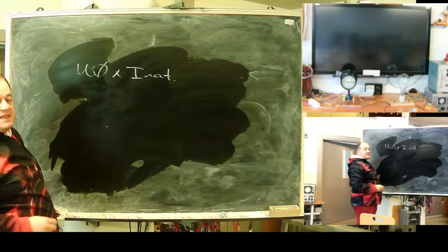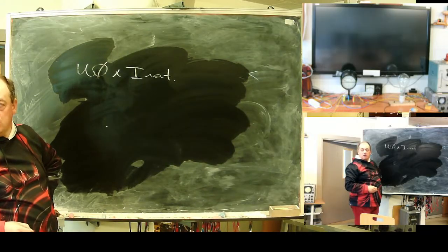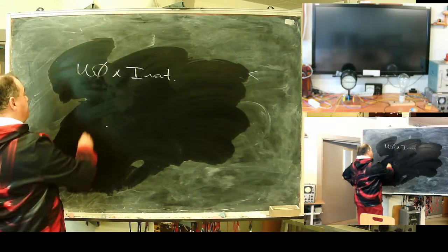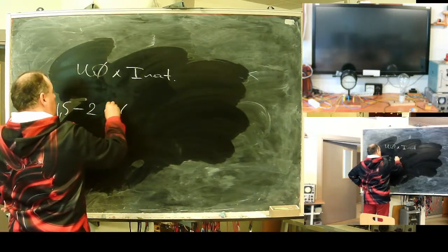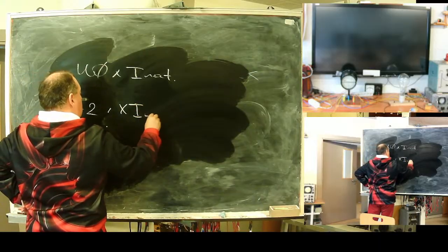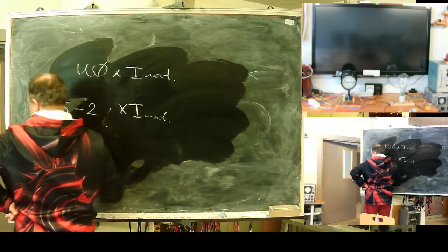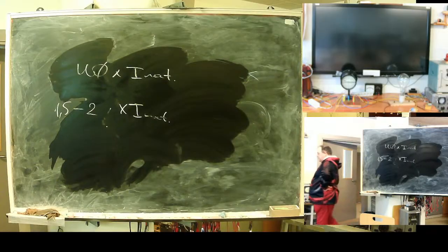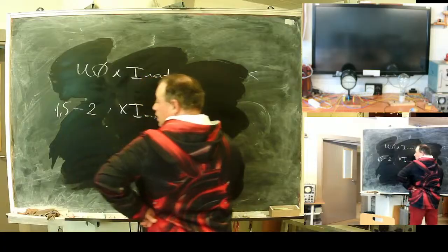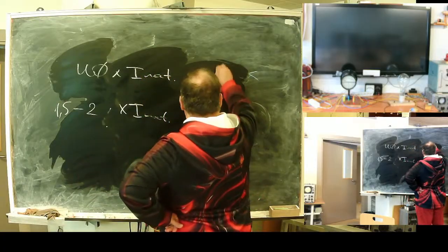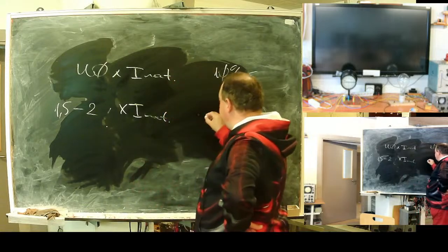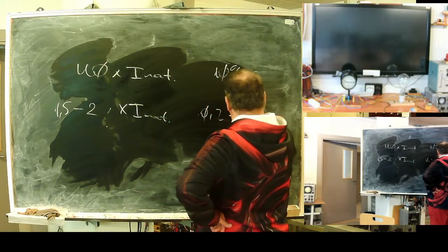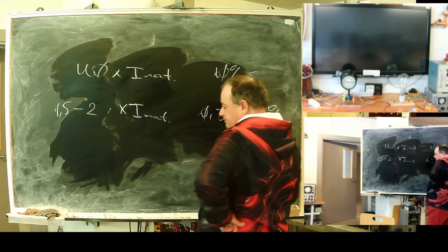For metering and monitoring purposes, 1.5 to 2 times rate. But here your error margin is up to 10% for protection, while for metering it is 0 to 0.5%.